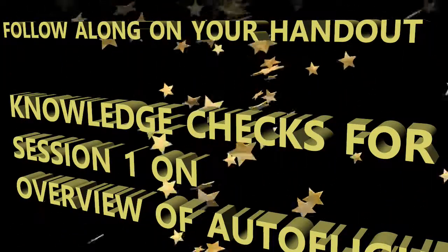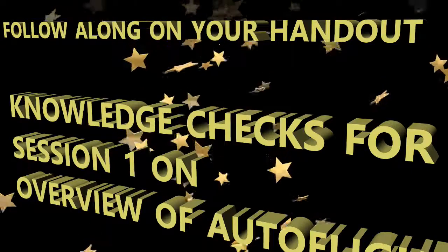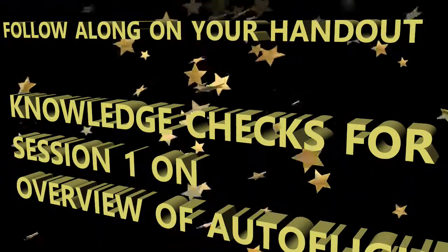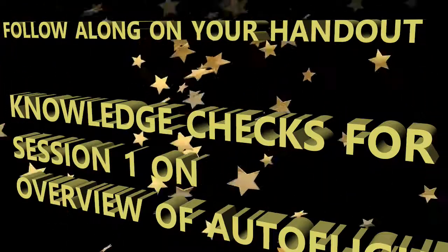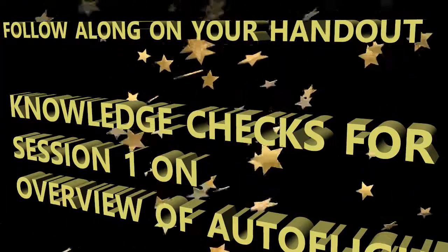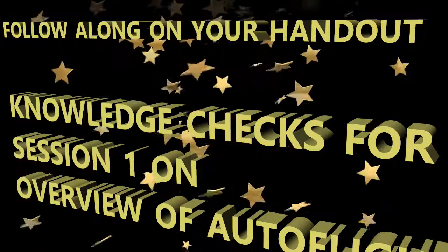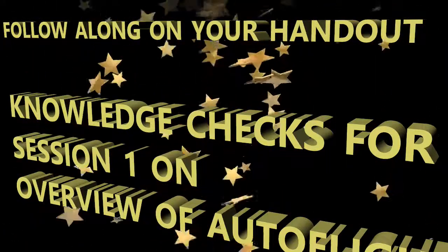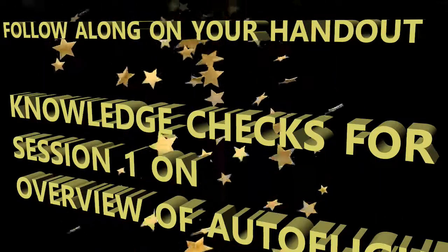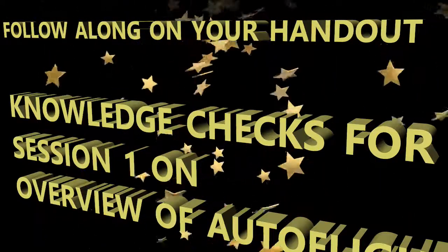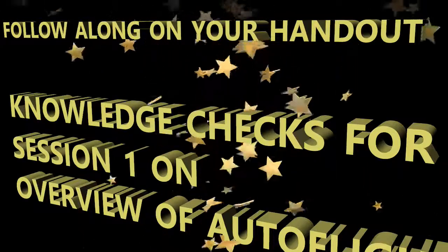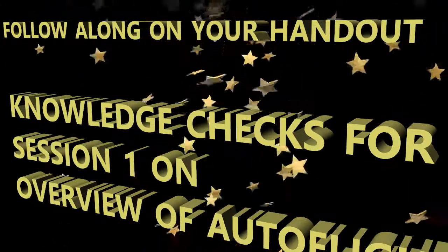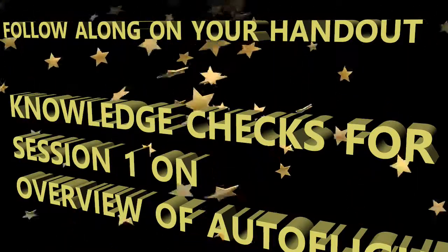Okay, is it the FAC or the FMGC? It's going to be the flight augmentation computer. Anything having to do with management and guidance, we'll get into, and of course our next session is going to be on the actual augmentation computer. But there are different things that it does to protect, and in this case, the FAC is responsible. Your flight augmentation computer is responsible for the protection of the flight envelope and also for rudder control.